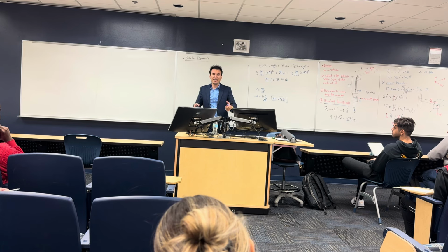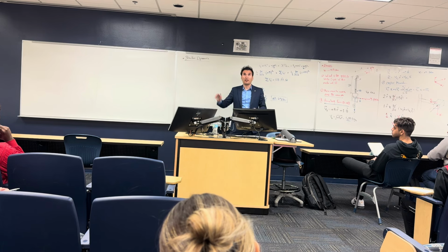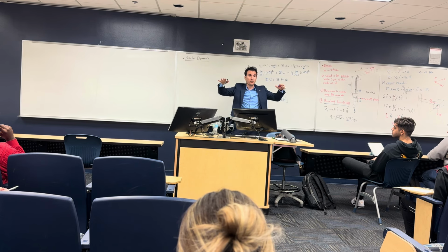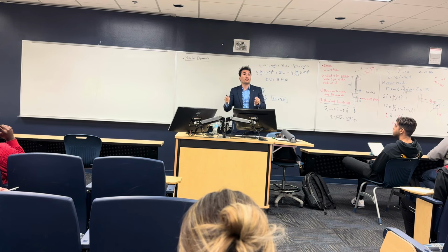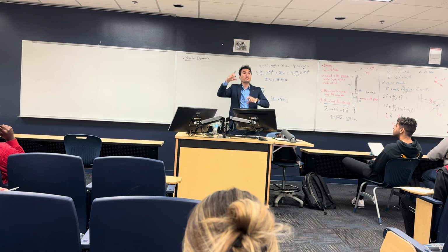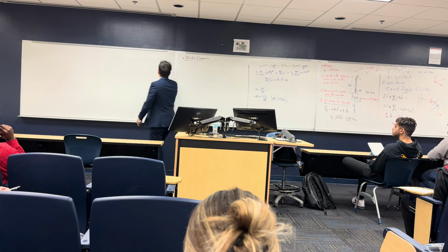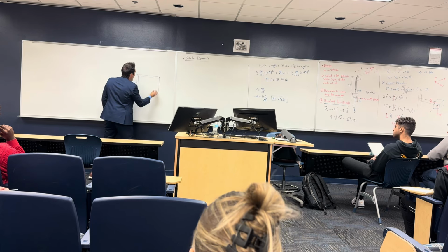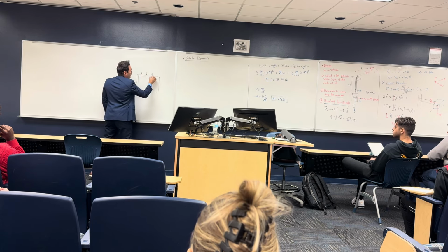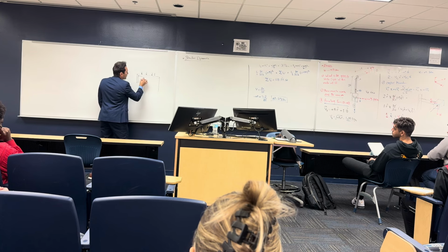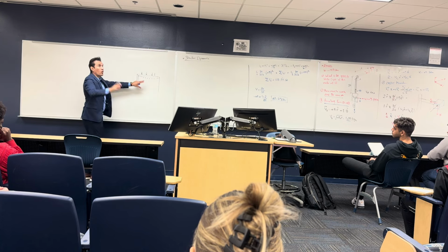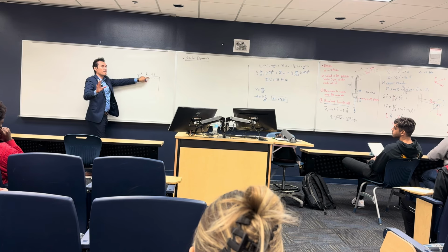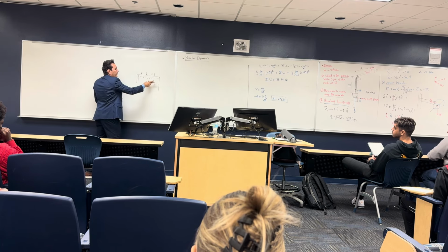But even with that, when somebody walks on some floors, like my neighbors walking over there, I can hear them and feel the whole thing moving. So we need to put a limitation on the displacement of the floor. If this is my floor and I put all my loads on it, it is going to deflect like this. This displacement is very, very small, relative to the length.